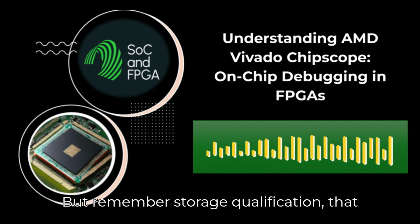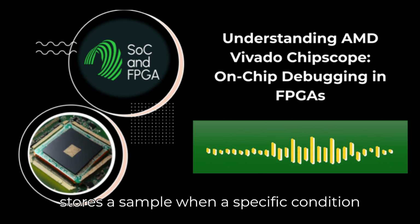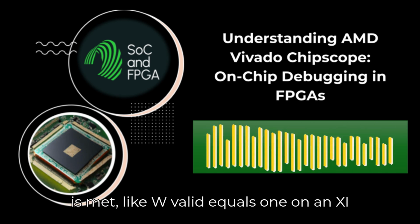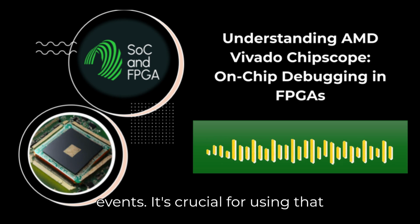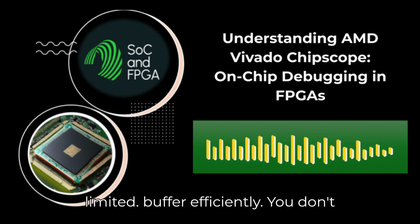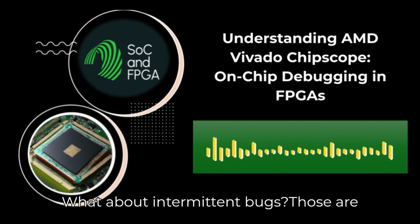But remember storage qualification. That advanced feature where the ILA only stores a sample when a specific condition is met, like W valid equals 1 on an AXI bus. Right, saving buffer space for sparse events. It's crucial for using that limited RAM buffer efficiently. You don't want it filled with junk before the interesting event happens. Makes sense. What about intermittent bugs?